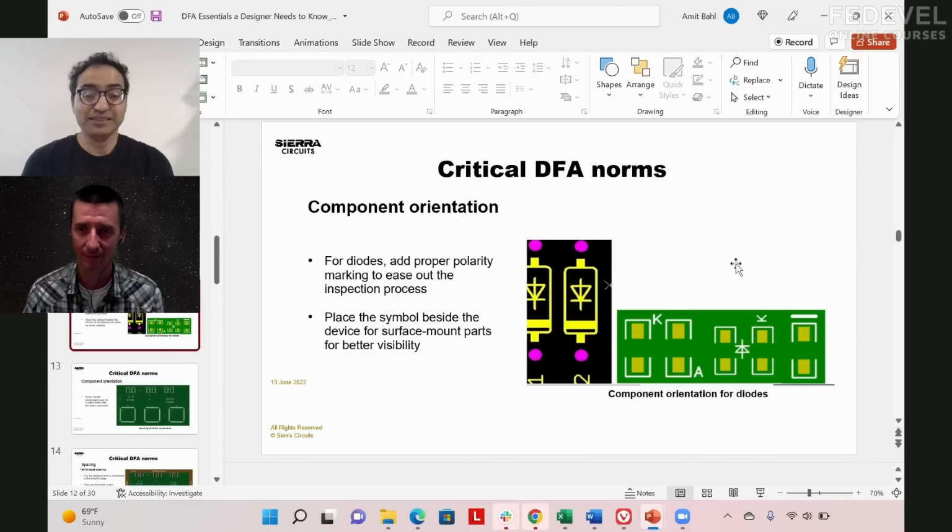Remember I was talking about having a baseline and then deviation from the baseline. Same thing with your drawings. If you put it down in your drawing, now the vendor has to say, I followed your drawing, or I didn't follow your drawing, and this is what I didn't follow. That serves as the baseline, which is the most important thing. If you don't provide any assembly drawing or just a few points, then you're going to get whatever. You're not going to know what you get.